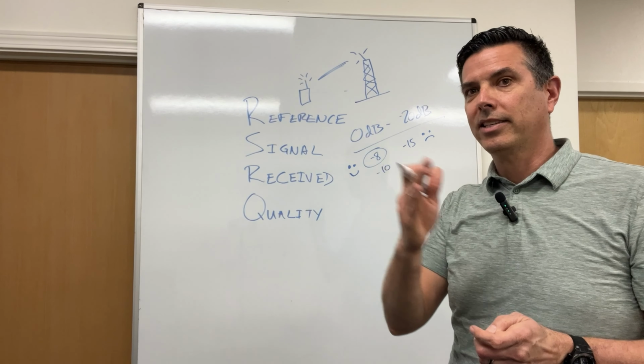You want to be that. You might see a couple of PCIs come in at the fringe by the windows, but if your DAS is designed and built right, and you are fully dominant over the macro networks, then this will be 100%. And that's your goal, to get as much dominance from the PCI you've created with the radio or you've pulled from a donor site. Physical channel identifier.